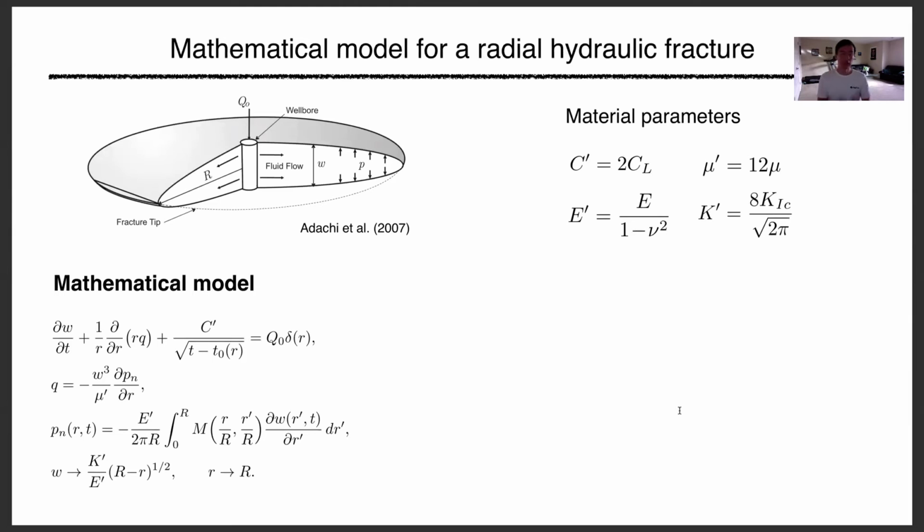So some equations here. We can outline these fracture regimes for simple fracture geometries. Today I'm going to talk about the radial fracture geometry and the PKN or constant height fracture geometries. Let's start with the radial and see how we get this definition of regimes and the parameters which govern the regimes. We start with the following mathematical model, the classical mathematical model for radial fracture. We have the Carter leak-off law implemented, a Newtonian fluid, so the cubic law for the flow, linear elasticity, and linear elastic fracture mechanics for propagation here at the bottom.